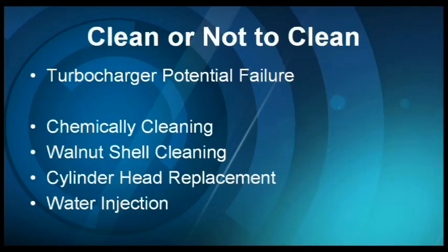Now, I would like to add something here that only one manufacturer has decided to fix this problem with. This year, BMW does have an M engine that has water injection. You can imagine whenever the engine is under a certain amount of load, if we would interject some water or water methanol injection, it would keep everything super clean. As a technician, I'm sure we've pulled the head on an engine with a blown head gasket, and we know exactly what cylinder the coolant has been going into, because that cylinder, spark plug, valves will be whistle clean.